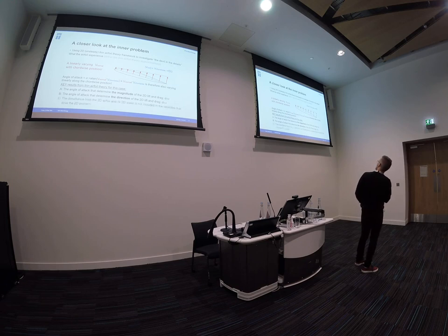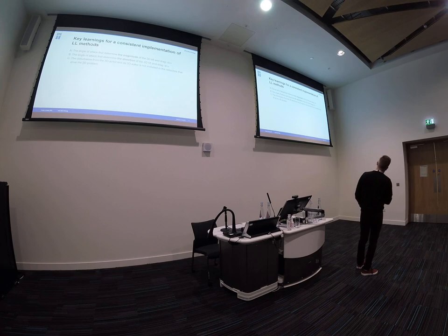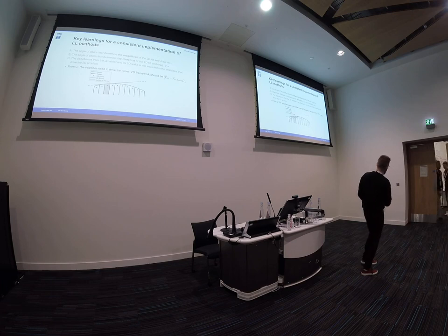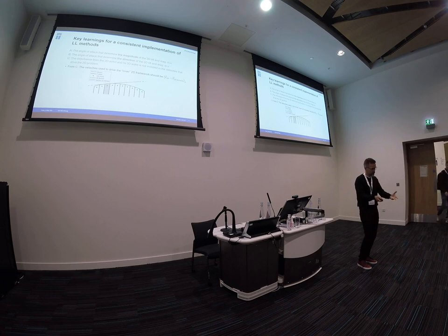So the driver of the inner thin airfoil problem does not include the disturbances of the airfoil itself. You think of that as an engine: you put something in, you get some forces out. So that's to keep in the back of the mind when doing the lifting line stuff. So from this last point, since you are not supposed to include the velocities that the 2D vortex system induces,